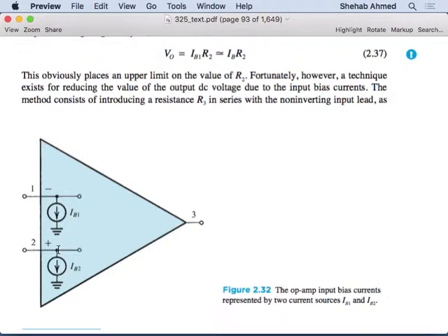They haven't even started to operate, they're just getting ready. Just for them to be ready, they require some bias currents. It's not due to the fact that your input impedance is low or high. This is due to the fact that you have transistors inside this block. Okay, so bias currents.